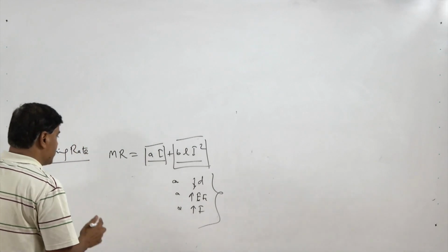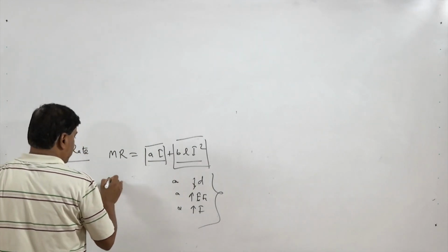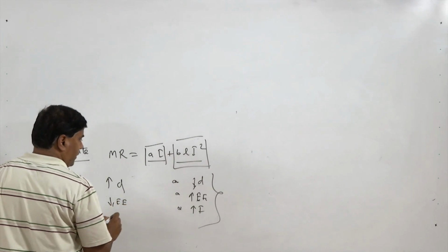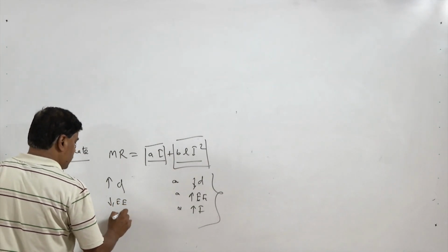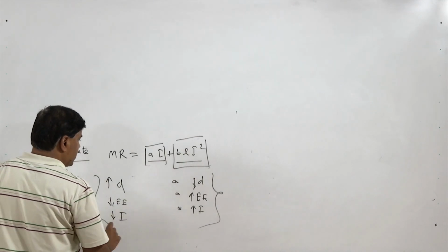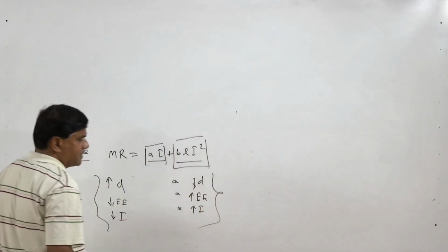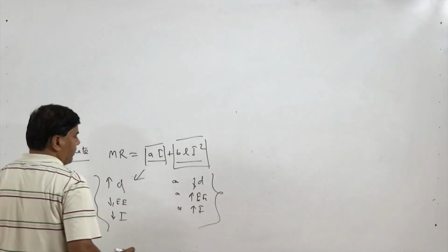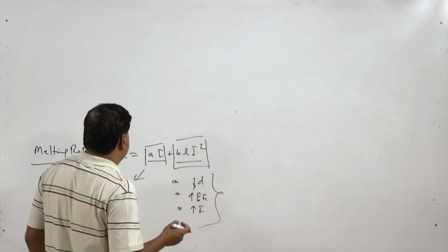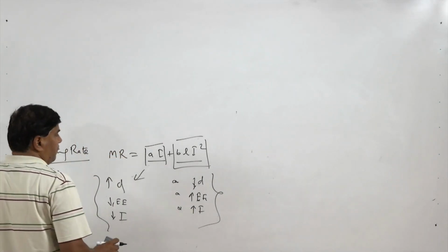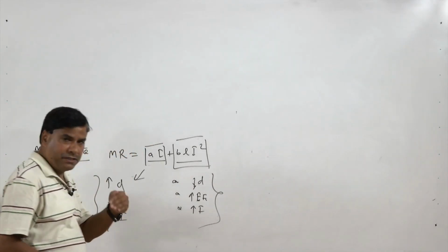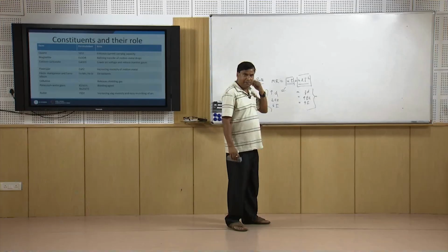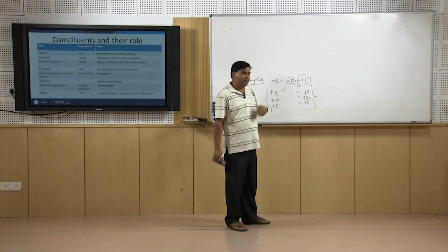If the conditions are just reversed, where the diameter is large, the electrode extension is short and the welding current is also low, in that case the role of the second factor is somewhat reduced, and you will see that the first factor is dominating or governing the melting rate. But it does not mean that we can achieve any kind of melting rate just by adjusting the welding current, because there are a number of factors that limit the lower and the higher levels of the welding current which can be used.